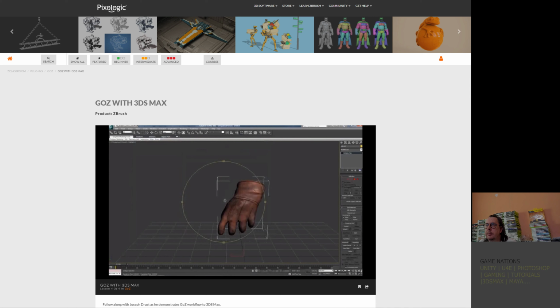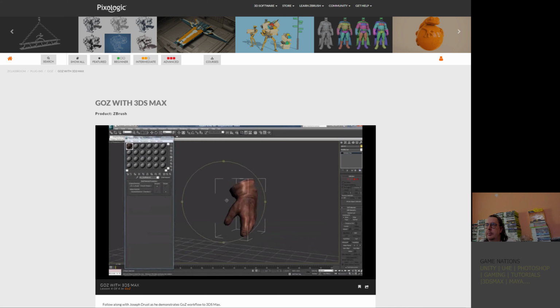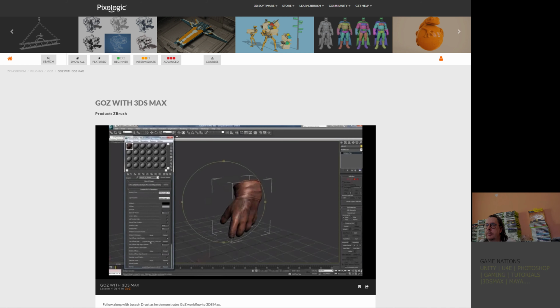Now, if I open up the material browser and we select the icon and I click the model, you can see that it actually has a shell material applied to it. So underneath the original material we have a DirectX 9 shader being applied, and this is actually linking the diffuse map and the normal map. If we go to the baked material, you see it's just a standard material, and if we go to maps, you'll see it has the diffuse, the bump, and underneath the mental ray connection we have a displacement map linked up.